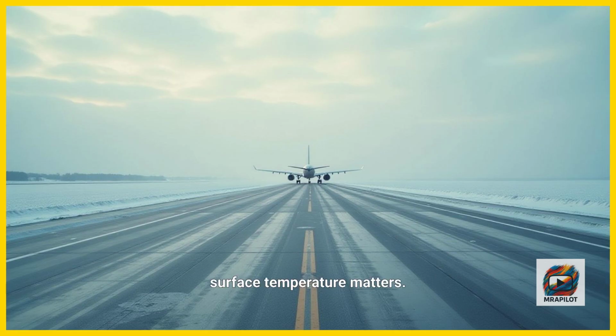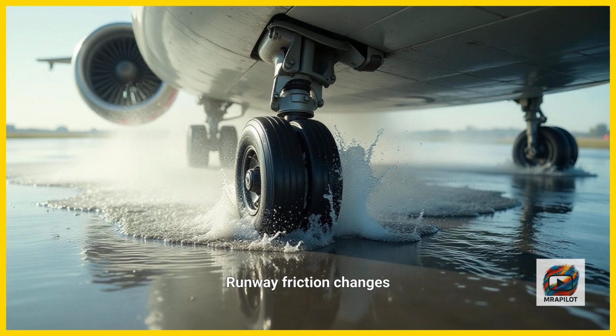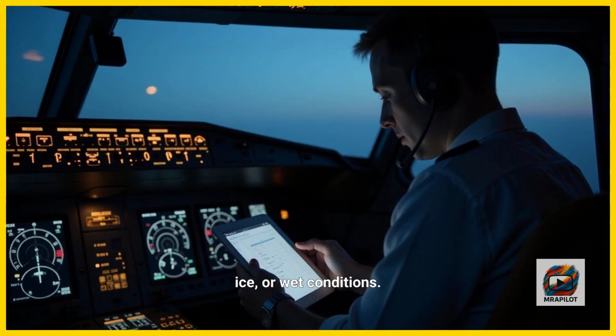Temperature also influences icing conditions. In moist air, if the temperature drops below 0 degrees Celsius, supercooled water droplets can freeze on contact with the aircraft, forming ice. This is most common between 0 degrees Celsius and minus 15 degrees Celsius, especially in stratiform and cumuliform clouds. Even on the ground, surface temperature matters. Runway friction changes dramatically with snow, ice, or wet conditions. Pilots must adjust their performance calculations to account for braking action and reduced acceleration.